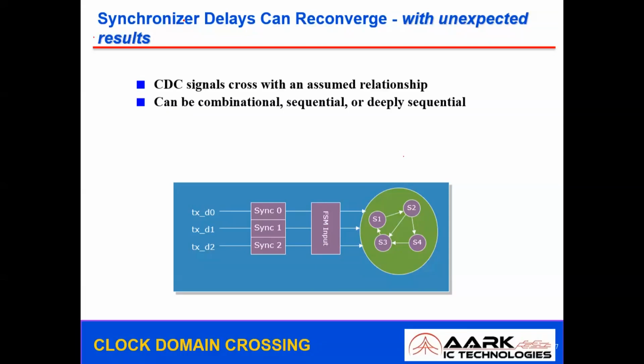And by using this FSM, we are going to synchronize the data which are available at different stages, which are violating the metastable conditions. These are properly synchronized with an FSM. As shown in the figure, I'm not going into much detail on the design, as it takes a lot of time to understand the complete design of this FSM.